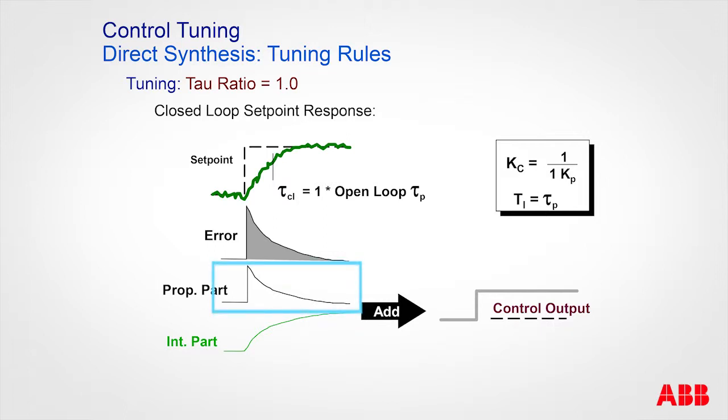It's proportional to the error. That's what proportional does. Remember what integral does? Integral is the area under the curve. In the last series, we always showed a step change in the error. That's why the integral was a slope. But here, the area actually goes to 0. So look at the integral. It comes up and stops.